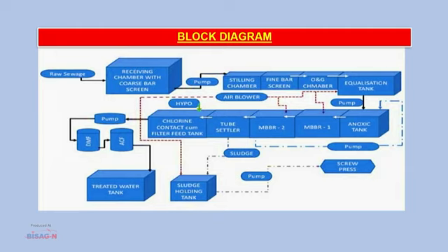Then stage 4 is the stilling. Stilling is done to reduce the velocity and to maintain the laminar flow. Sewage is received in the stilling chamber. Then stage 5. The sewage goes from the stilling chamber through a fine screen to the oil and grease chamber.